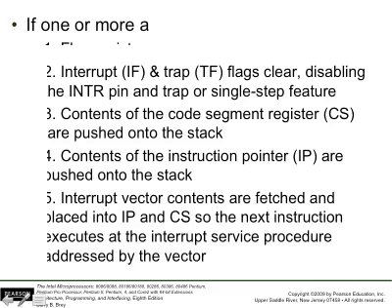And then it will push CS and IP onto the stack, because that's to record the proper return address. And then it will go to the interrupt vector table to retrieve the new CS and IP, and that CS:IP should be used to fetch the next instruction. And of course, in order to do that, the processor has to know what the interrupt number is, right? Because it uses that number as an index to the interrupt vector table.